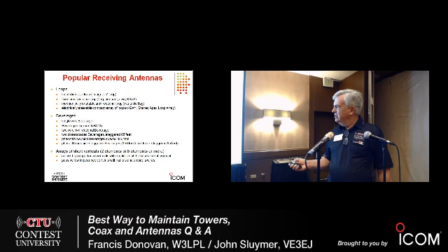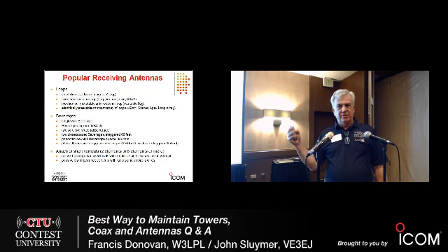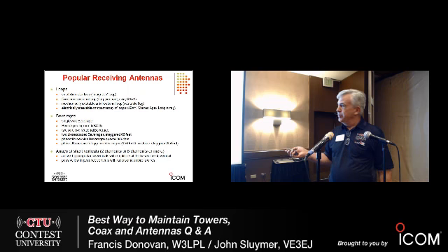So they're quite practical. I don't think I mentioned at the beginning of the presentations that all of the dimensions I'll speak about, so I don't have to keep scaling antennas from 160 to 80 to 40. All these antennas will work on any of the lower bands. All the dimensions I'll mention here are for 160, but if you're interested in 80, you can just divide those dimensions in half. So you can build a really good 80-meter receiving array, only 35 feet on a side. You can also scale these same dimensions to 40. But I'm not going to go through all those dimensions as I speak about this.